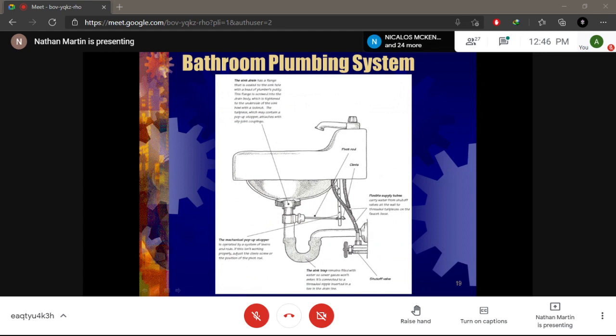And you have your flex hose or your flex tube, right? The flex hose is more recent. It's more being used compared to your flex tube. The flex tube is a gray one. For older installations, you will see the flex tube, but for newer installations, because the flex tubes always burst after a period of time, plumbers are now using the flex hose much more, right?